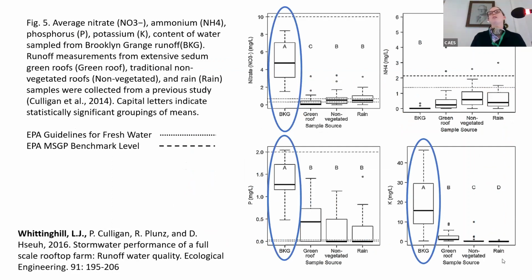Stormwater quality improvements are another benefit of green roofs. And there are a number of caveats that go into how well a green roof can improve stormwater quality, including management practices like fertilization, inclusion of compost or other organic matter in the rooftop, as well as roof age and other factors like what's settling on the roof between storms and what roof pipes are made out of.